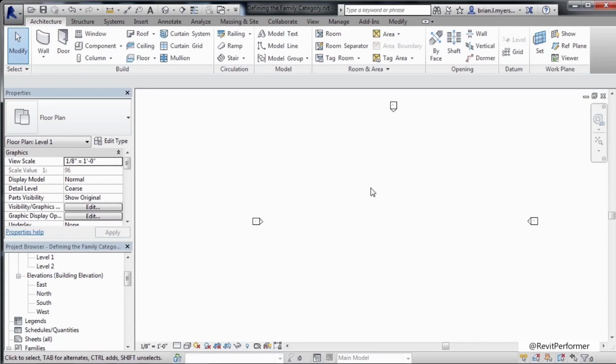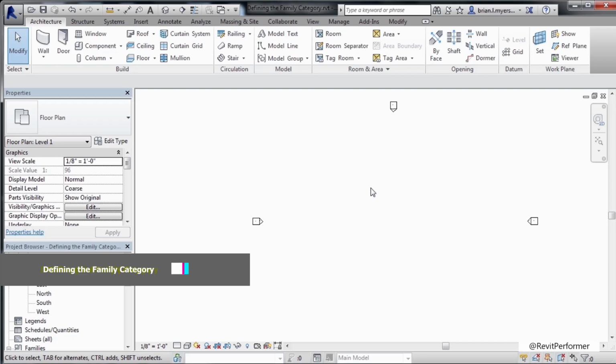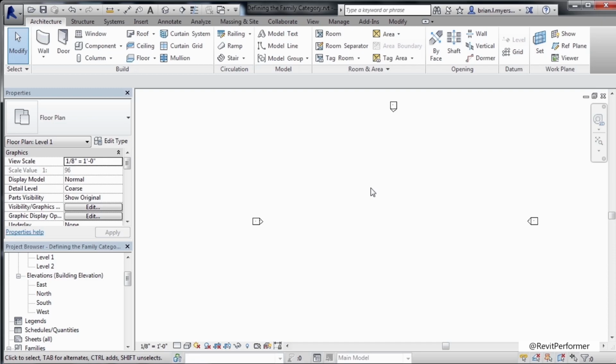Revit families have a variety of different categories that they fall into, such as doors, windows, and mechanical equipment. Each category affects the way that Revit organizes them as well as schedules them. One of the things that you'll find is that as you're downloading families from online resources, sometimes you'll end up getting an odd category for your Revit family. And it is possible to recategorize those Revit families to meet a category which makes more sense for that kind